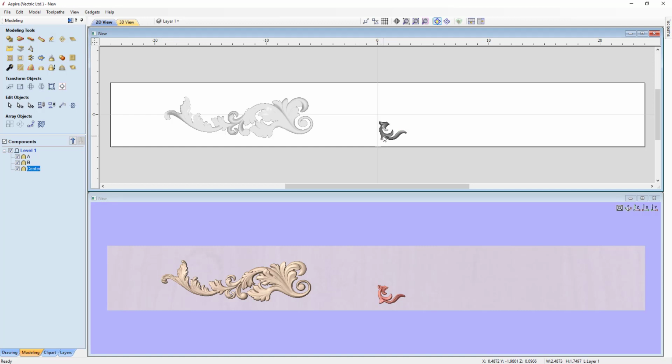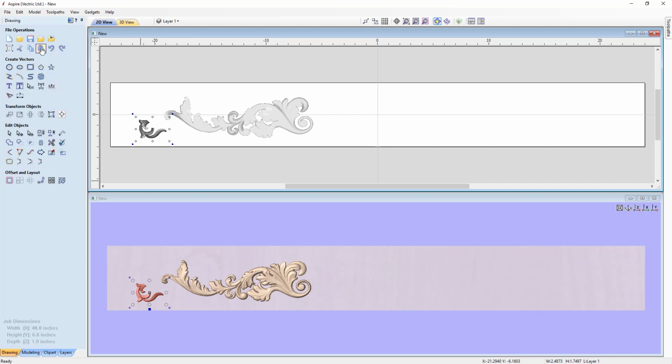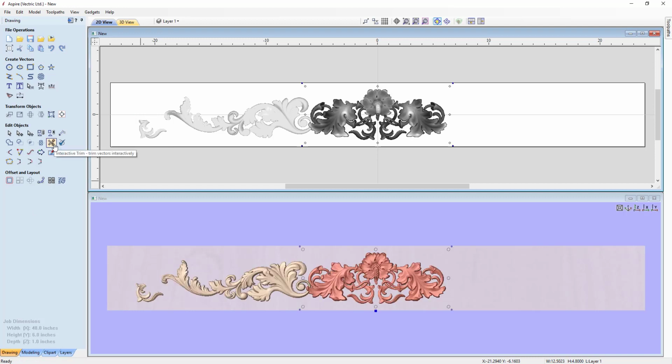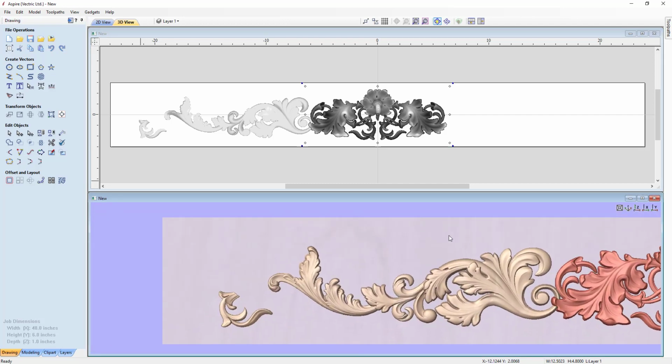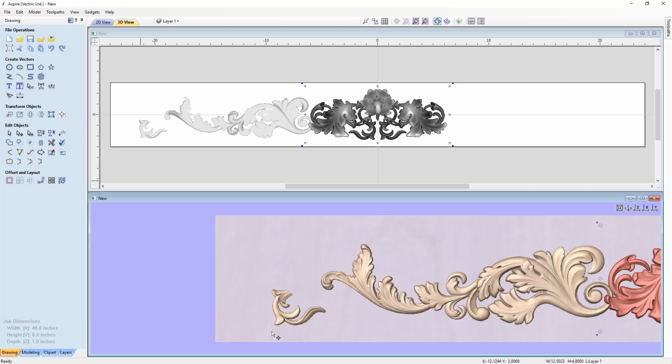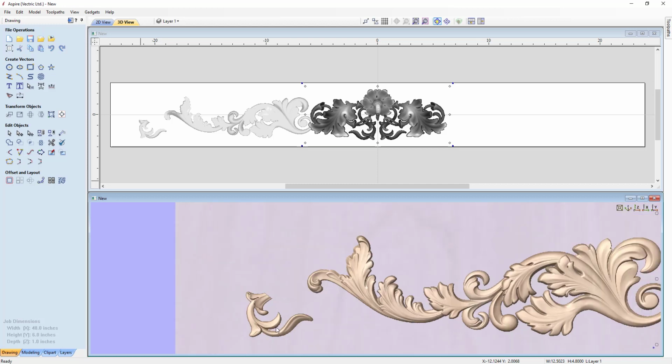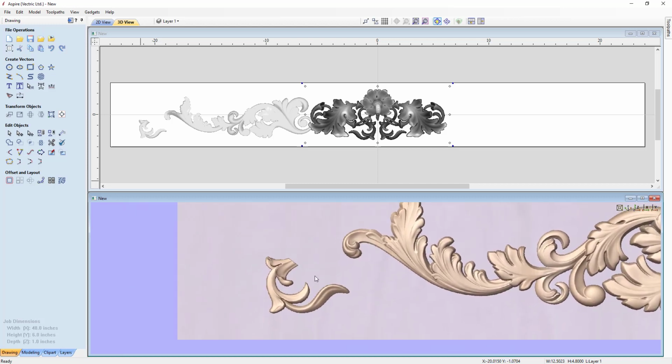Let's grab that piece, slide it over here. And then before we forget, we better paste that center back in place again. We can go back to our drawing tab and we can choose paste from our clipboard, or we can just hold down our Control and V key on our keyboard and we'll paste it right back in place again. Now let's zoom in to the end of our layout using our scroll wheel, and then again holding down the left and middle mouse buttons and pulling to our right.